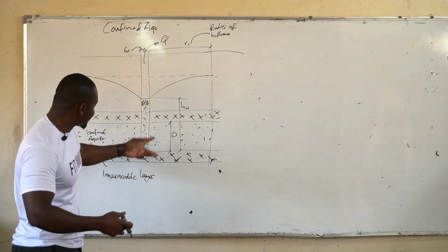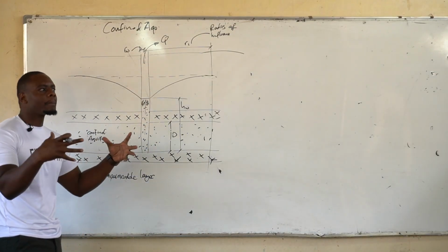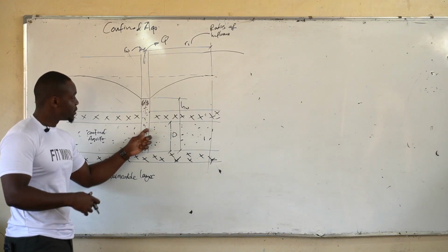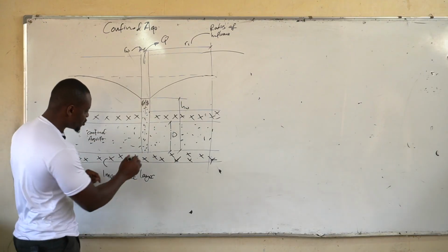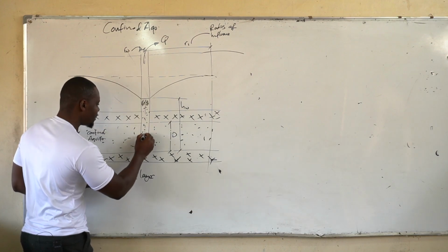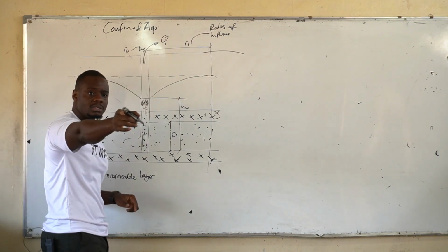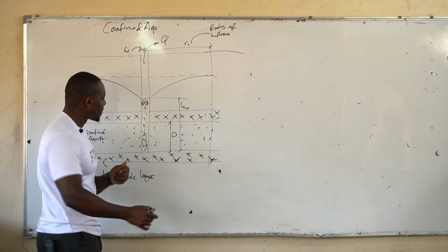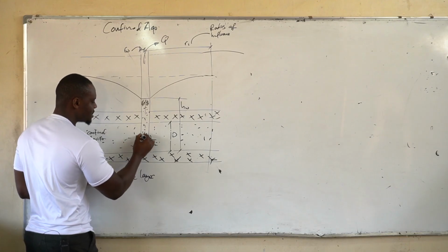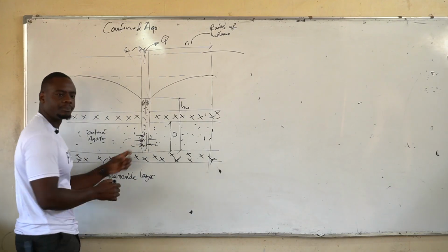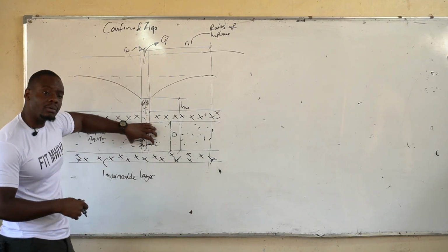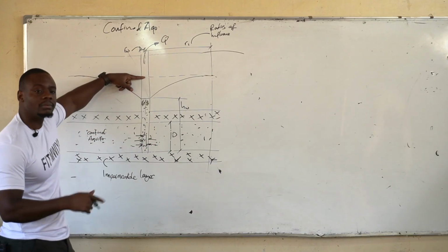Exactly. Why? Because this guy is a little bit protected. He's under some pressure, and we always have water coming from all directions. Because when you drill a borehole, what you do is that you drop your pump, and it just comes and sits somewhere there. All right? And then, of course, this pump will come with its own electrical cables and the pipes. When you run the pump, this guy draws water from all directions in a circular or radial manner. So it's pulling the water. But originally, the moment you just pump, this aquifer releases water to the water table